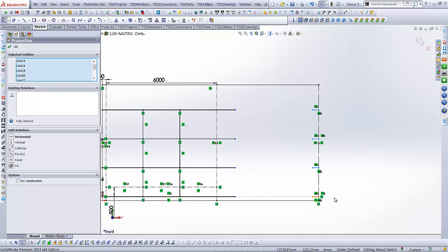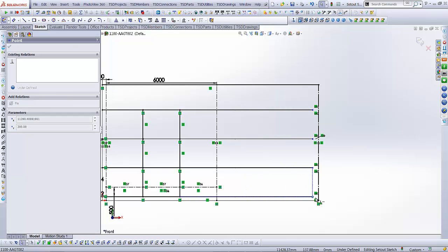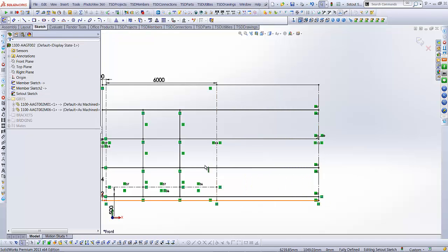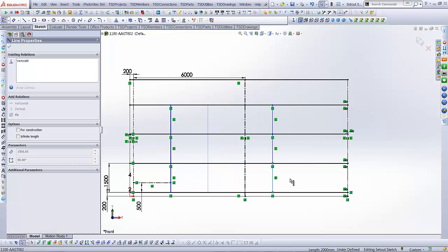The little return legs here, and I want to bring that over so that that sits there. Alright, now we've got 2 rows of bridging here. I'm just going to bring 1 row of bridging over so that we can reuse it. Okay, so I'm just going to remove the equals out of there and bring this over here, so now we've got 1 row of bridging there.